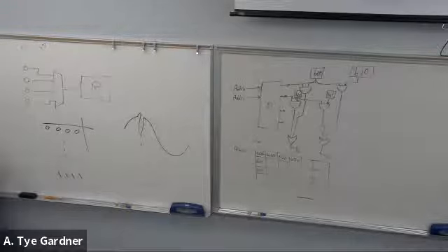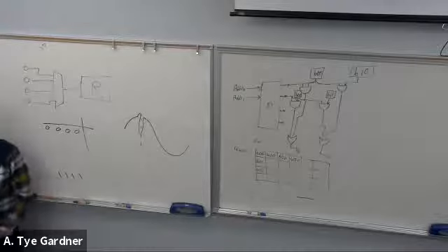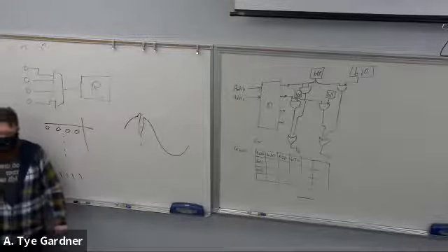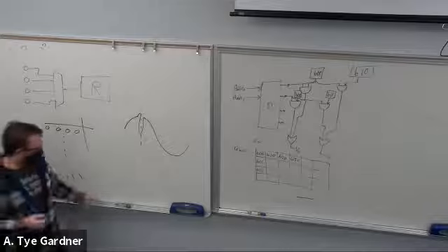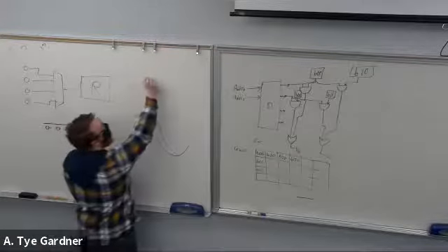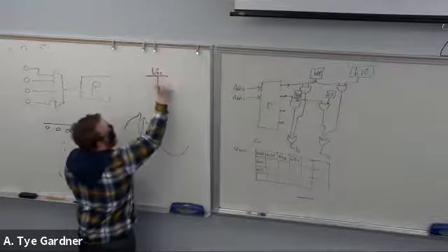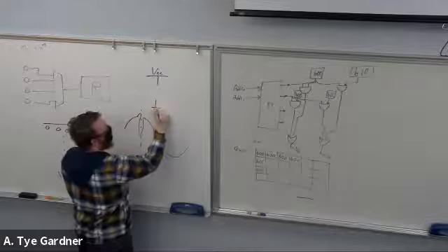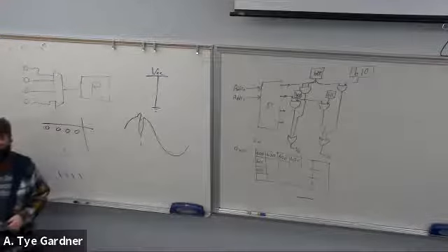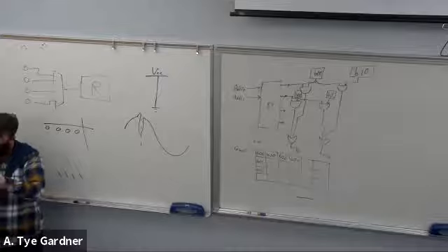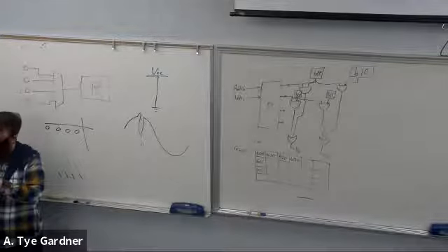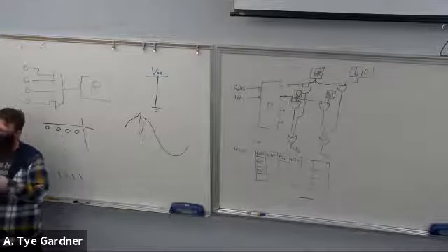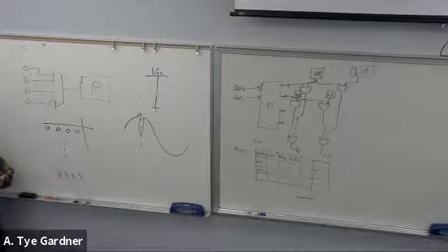And you may have seen this type of phenomenon in your desktop measurements already in the lab, where if you've hooked up the circuit wrong and you end up with something like VCC to ground, so power to ground, with nothing in between. Then you're looking at your power supply and going, huh, it says 2.5 volts, but I've told it to be 5. Well, what's happening is it doesn't have enough current. It can't supply enough current in order to maintain the voltage that you set it at.